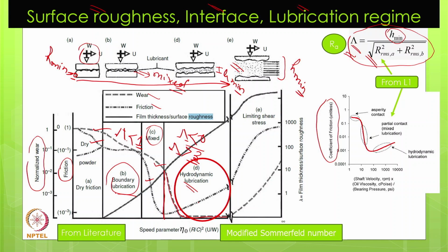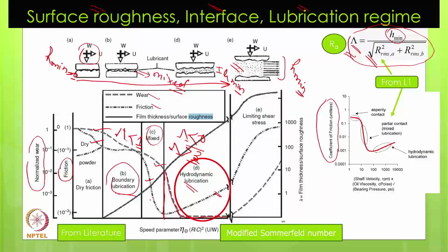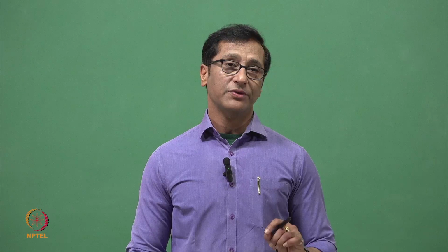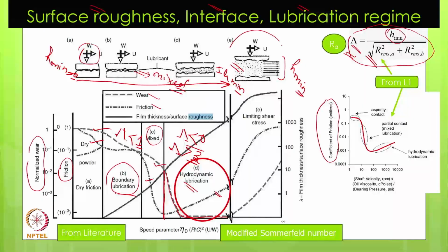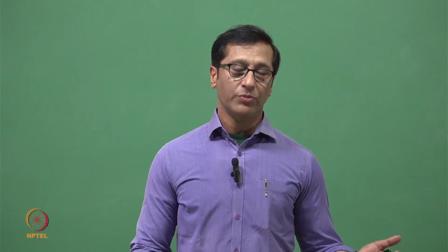That's why we say we don't want an increase in friction, because energy consumption is also important, not wear only. Under mixed lubrication they follow a similar trend, while in the hydrodynamic regime, where the two surfaces are completely separated, they do not follow the same trend; wear becomes zero and only friction is important.